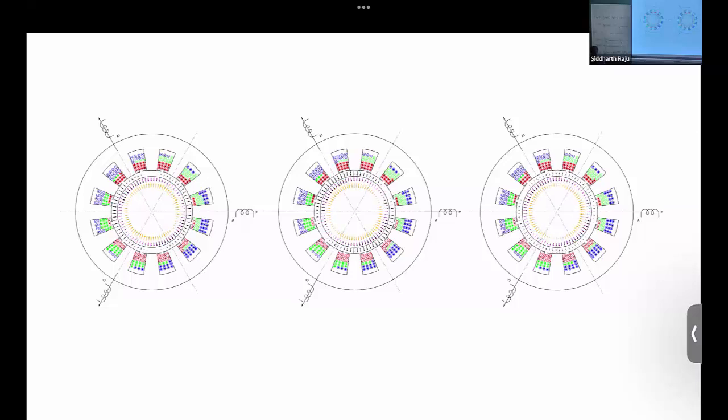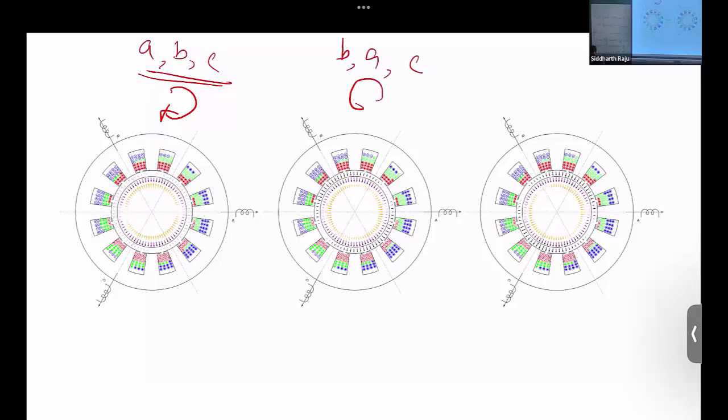So if you do two swaps, let's say A, B, C is the sequence. So here in your wall outlet, let's say you have three terminals marked A phase, B phase, C phase, and you connect your motor A phase, B phase, C phase exactly to the correct terminals, then let it rotate in one direction. If this is the direction it rotates, all I have to do is swap B and A, then it would rotate in the opposite direction. If I do one more swap, BCA, it would go back to the original rotation again, right? So it's a singular swap. If you do two swaps, you again go to the same original rotation. It is just the initial starting angle would be different depending on the rotation that you do.